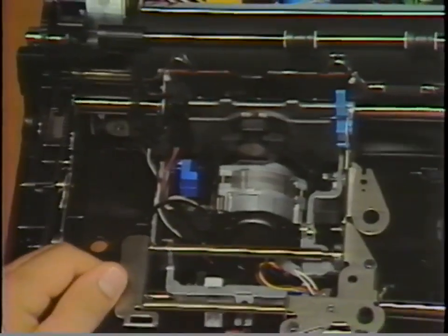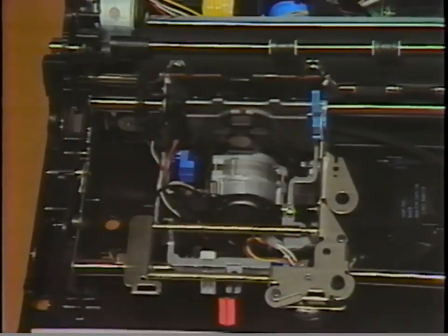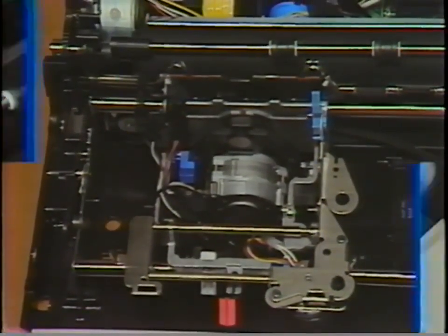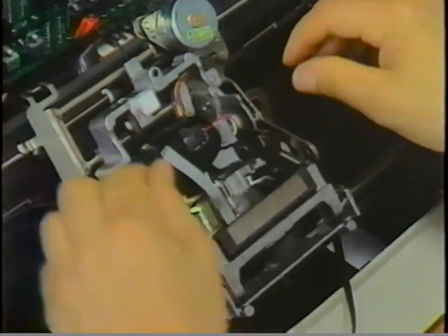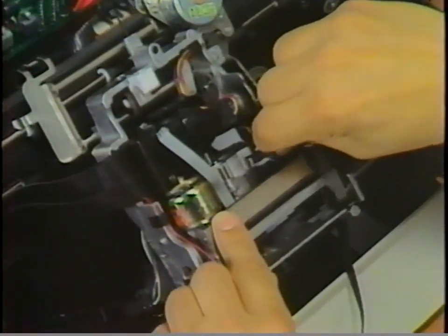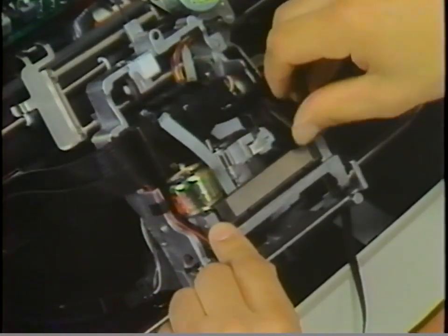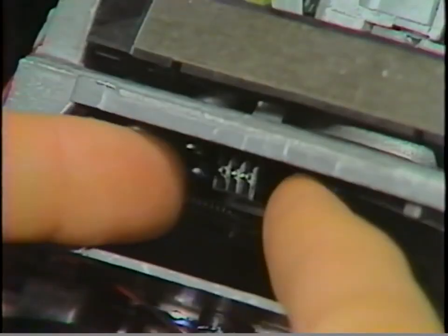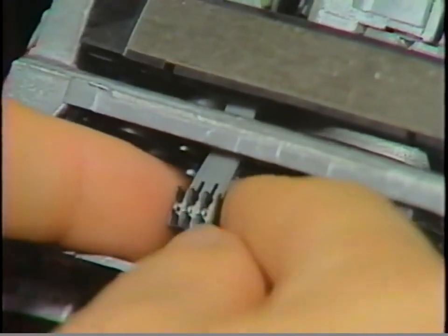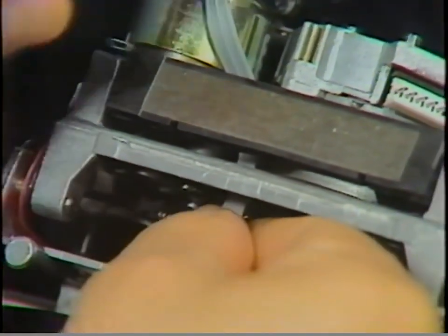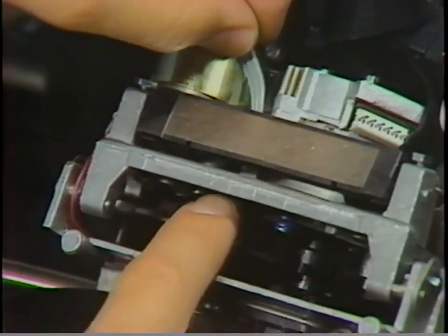Remove the carrier, turn it over, and place it so the transport belt bracket rests on the front rail and the ribbon plate rests on the paper bale. Unplug the selection motor connector. Next, unplug the homing sensor connector from the bottom of the sensor bracket and pull the sensor connector cable out of the selection plate.